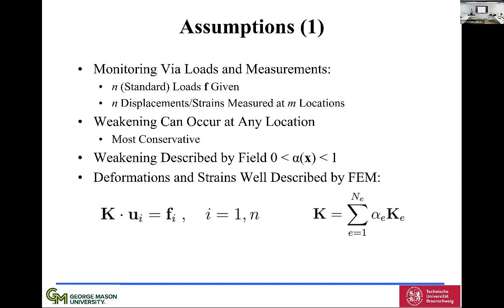Okay, so before I go on, let's see what the assumptions are that we're going to make. We're going to assume that we are monitoring via loads and measurements. So we have n standard loads. It's the same truck or the same train that I pass over the bridge every year. And I have m locations where I have some kind of sensor that gives me data based on the forces that I have. Could be displacement, strain, anything else.